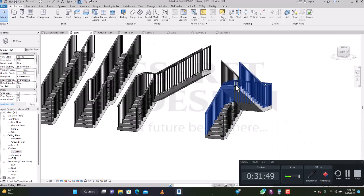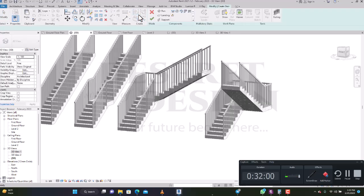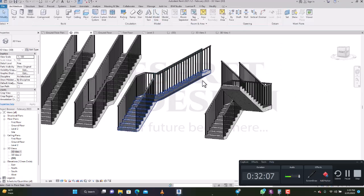So question. With this, you didn't change the location line? No, I'm still using the default. Oh, okay. No, I'm using right. Right. Okay. So it doesn't matter where you are holding. The only thing is that where you are holding, when you are constructing, do you get what you want? If you are not getting what you want, you can decide to change your location line. Okay? Any question?